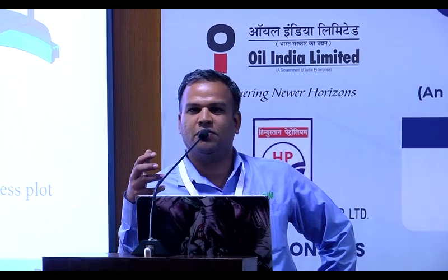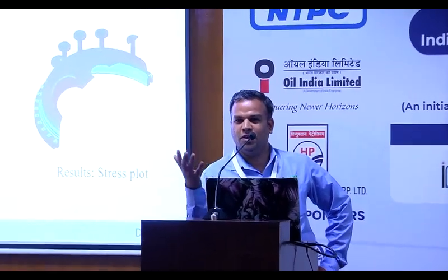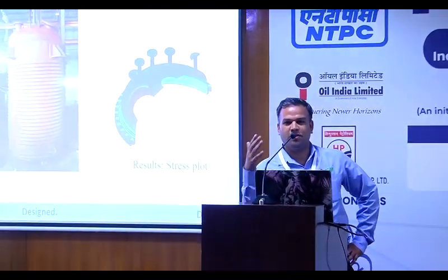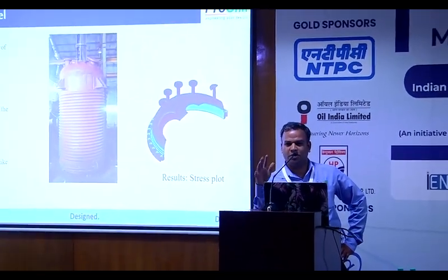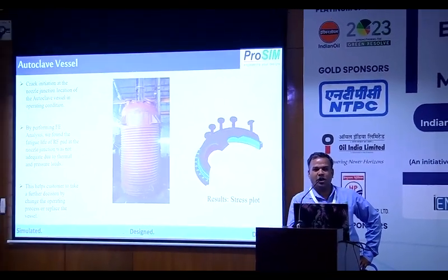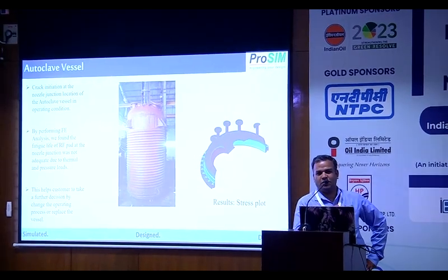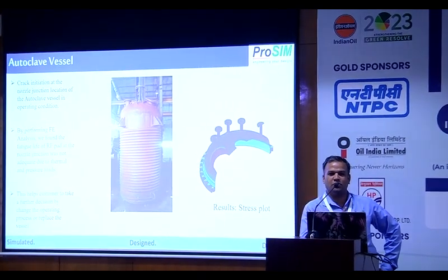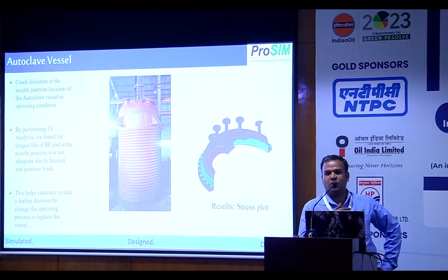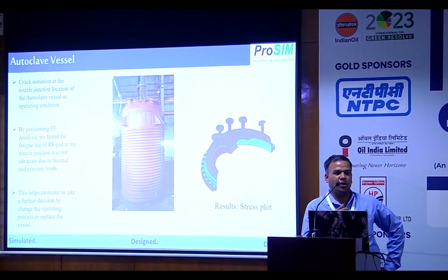We collected the data from the asset integrity team. We built a CAD model. Many of you know the general procedure for the FEA, so no need to repeat the full procedure. Taking care of the weld joints and the nozzles with the shell, with the corrosion and all, we applied the applicable process pressure and boundary conditions.